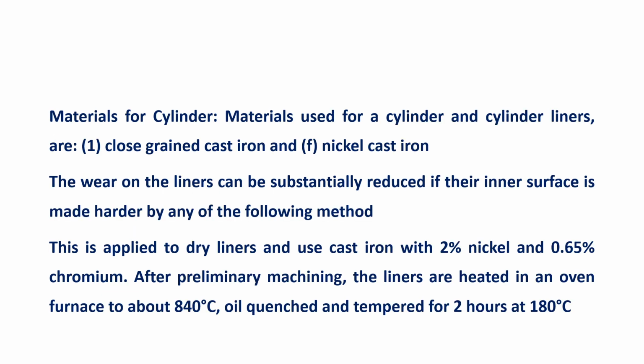What materials can you have? You can go for close-grained cast iron and also nickel cast iron. The wear on the liners can be substantially reduced if the inner surface is made harder. We have one or two methods. I will describe one method which is very prominently used, and it is applicable to dry liners.